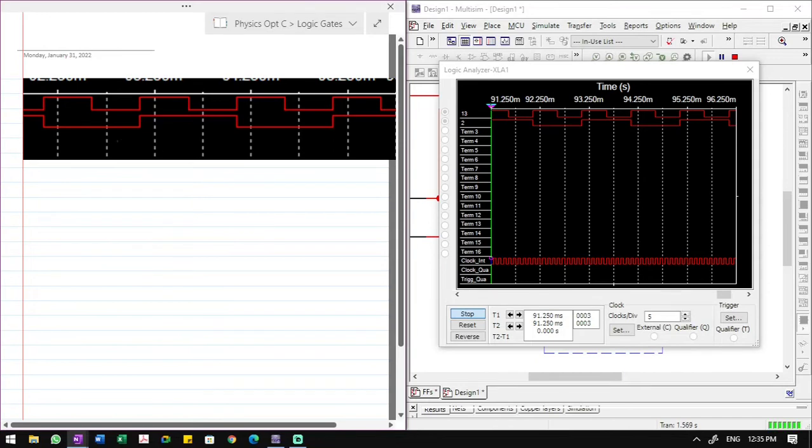Right. So this is one complete cycle here. If I go like this here, this is one complete cycle there. Right? I need to go up now. That's one complete cycle there. But on the other graph, this similar shape complete cycle is this here, which is obviously what? Twice as wide. So the periodic time of the output of this circuit here is double the periodic time of the input. Am I saying that correctly? Yeah. Good. So it means now it has half of the frequency.